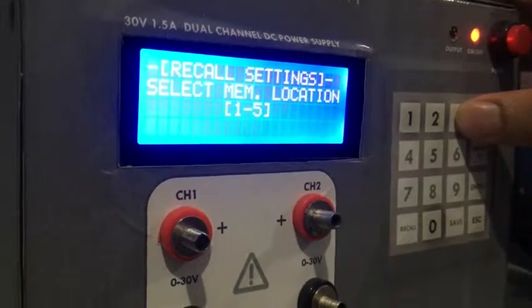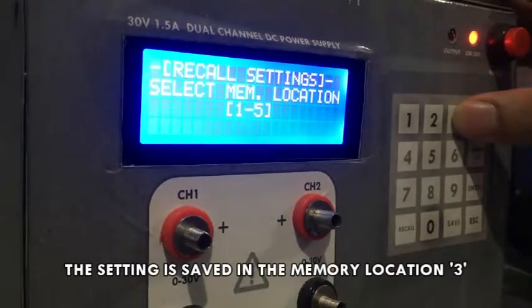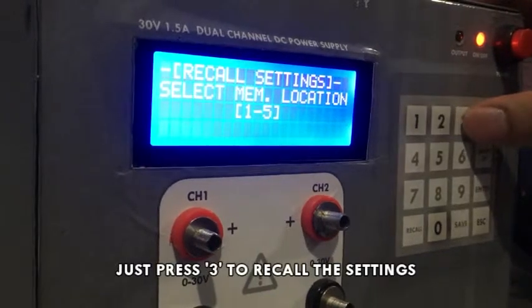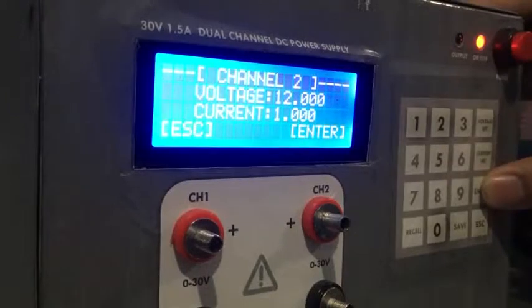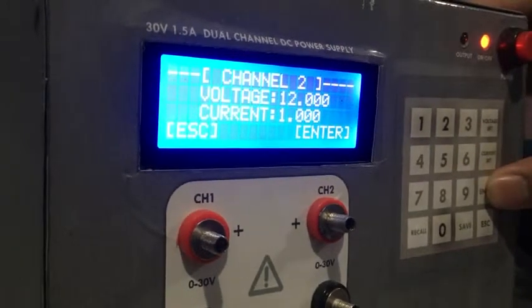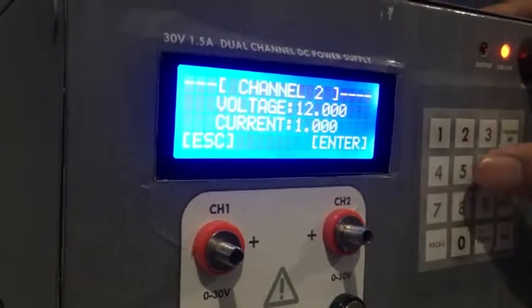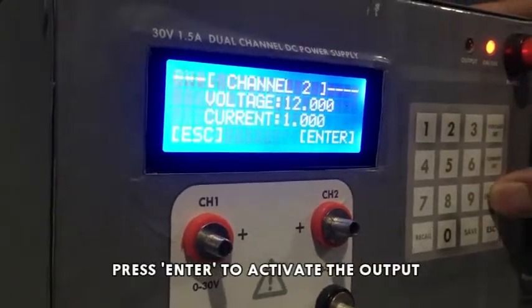Earlier, I saved the voltage and current settings in memory location number 3. And I will press number 3 to recall the settings. There, we can see that the settings are recalled. Just press enter to activate the output.